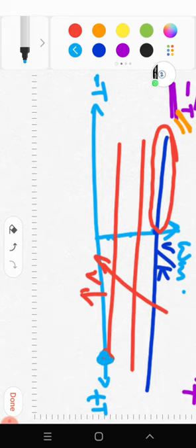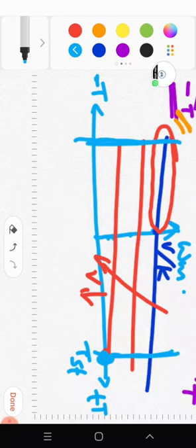when the speed is 0, there is some torque, so this should be the starting torque. At the max this could be double that of the rated. Current in the machine can be double that of the rated, so torque also can be double that of the rated. So whether it is a motoring operation or a braking operation, these are the limits of the torque or the limits of the motor current.